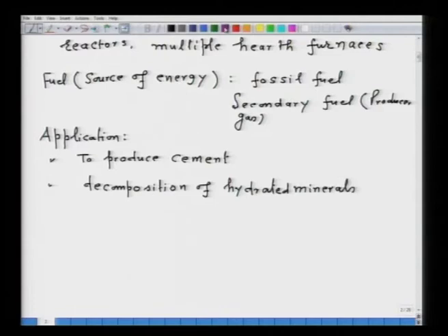Now, this decomposition is done for one purpose, could be we want to make Al2O3 refractory. Now, here bauxite is the material to produce Al2O3 refractory. Now, bauxite also contains water which is chemically combined. So, straight away you have to calcine it in order to produce an alumina which is free from water, and mind you, alumina is a very important refractory material in all pyrometallurgical extraction industry.